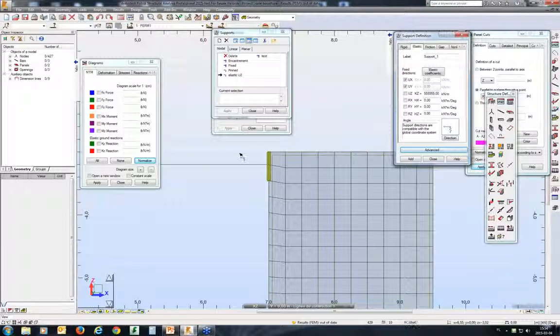Another question: with the model where you changed panels into bar elements, how did you connect the beam into the 3 nodes of the panel wall element? Francois responded, using the rigid link option. So 1 node is the master node at the end of the beam, and 2 nodes of the meshing are defined as slave nodes.